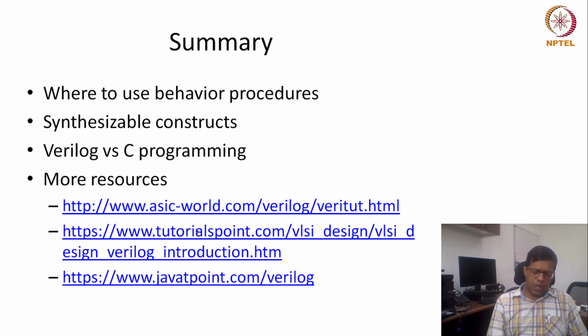Okay, so I would suggest using judiciously when we should use behavioral statements, and when we use data flow and structural statements. The ideal thing would be to use a mix of them. Sometimes we can use behavior statements; for example, for designing a flip-flop, you don't have options, you have to write behavior statements.